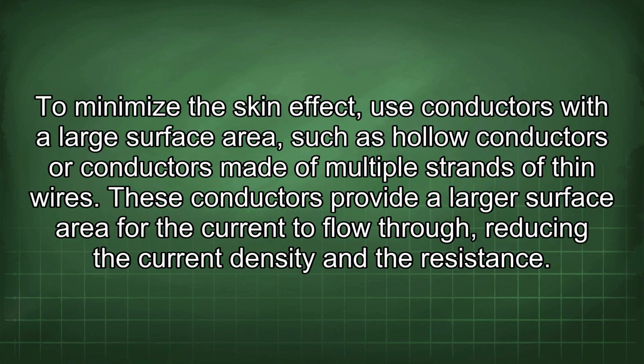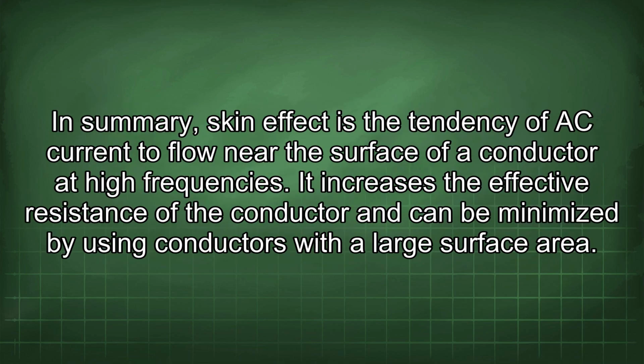To minimize the skin effect, use conductors with a large surface area, such as hollow conductors or conductors made of multiple strands of thin wires. These conductors provide a larger surface area for the current to flow through, reducing the current density and the resistance. In summary, skin effect is the tendency of AC current to flow near the surface of a conductor at high frequencies. It increases the effective resistance of the conductor and can be minimized by using conductors with a large surface area.